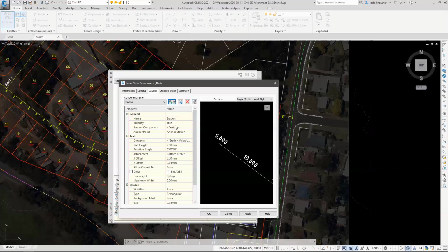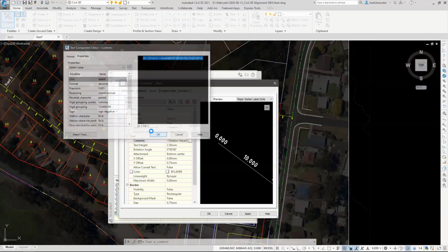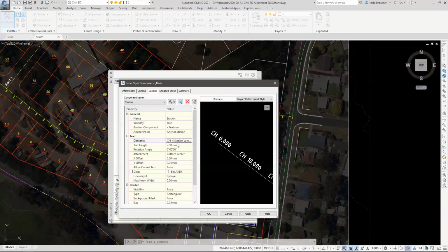Okay, so for the marker, I want the text to run perpendicular to the alignment direction, and I want the text to be 3, yep, but I want my CH marker in front, so I'll do that, so I get that. Height 2.5 mils, that's fine for this. I want the orientation of the text to flip around so that it runs up the alignment. It's either -90 or 270, so that it flips around and starts to run up the increasing alignment direction.